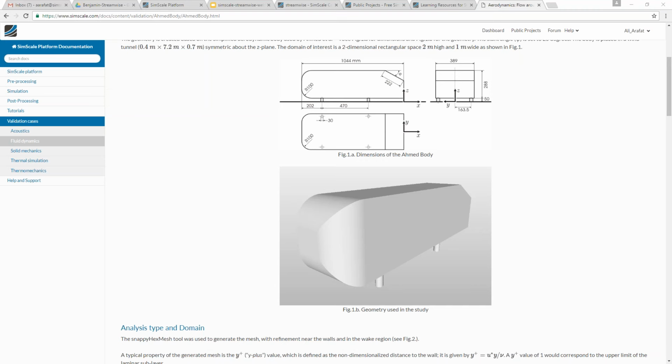Start from 2D streamlines or surface line integrated contours to analyzing the velocity vectors themselves. Also, if it's close to the boundaries and you're interested in calculating the separation point, you can calculate the wall shear stresses, and you can see when they're getting negative, that's the point of the separation and the reverse flow. So there are multiple methods that you can use depending on how detailed you want to go. Okay, I hope that answers the question.